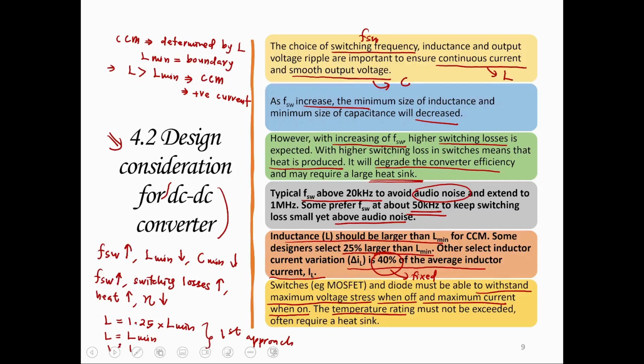Function of L, it will determine the boundary, the modes of operation for your converter. Okay, when L equals L min, this is the boundary mode.